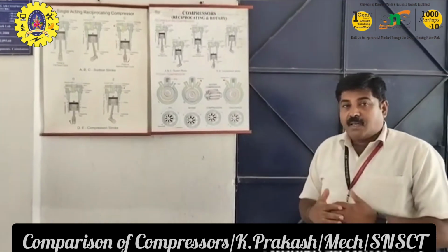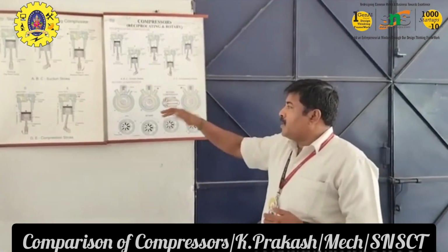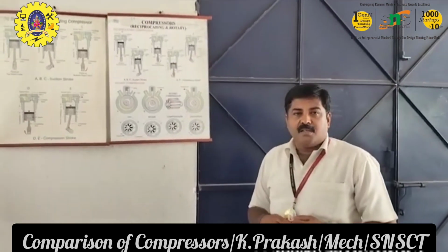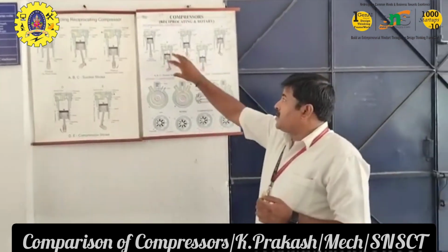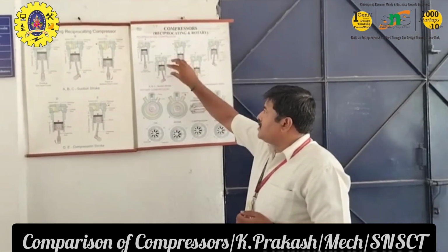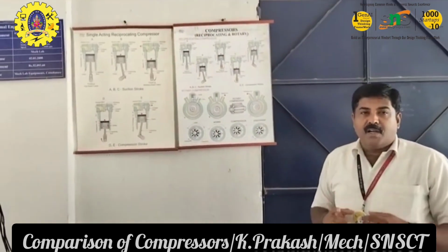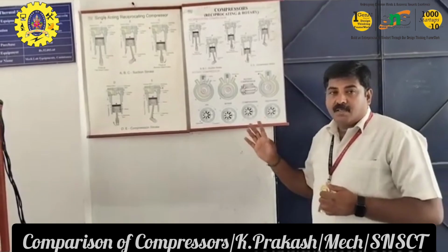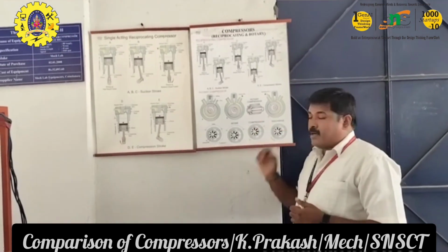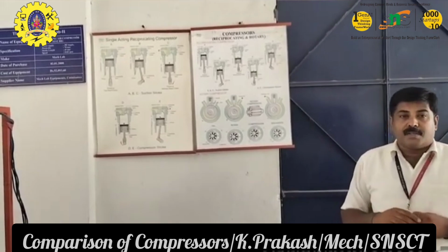And what are the factors compared between the reciprocating and the rotary compressors? The first thing is the pressure. Here the pressure is high, whereas the flow rate is less. The amount of air delivered by reciprocating compressors is less, whereas in the rotary compressors the air flow rate is very high when compared with the reciprocating compressors.